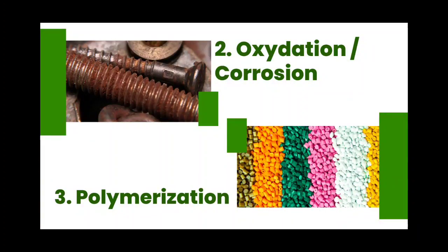Of these, the most important by far is the electrochemical corrosion of metals, in which the oxidation process is facilitated by the presence of a suitable electron acceptor, sometimes referred to in corrosion science as a depolarizer.